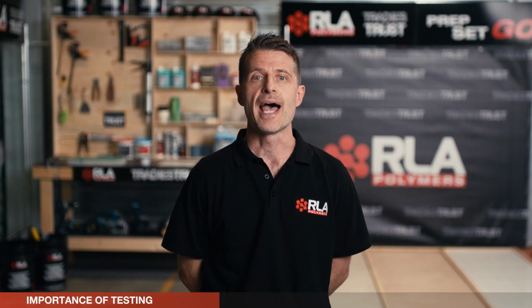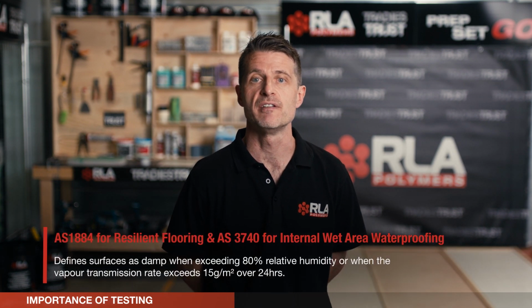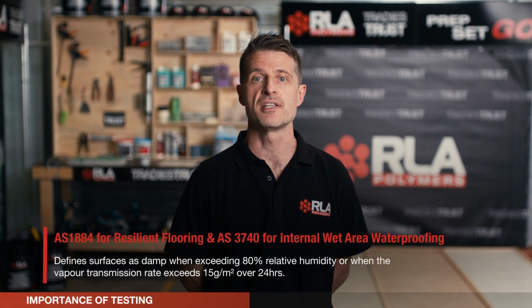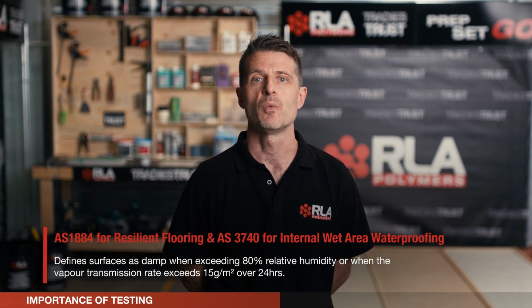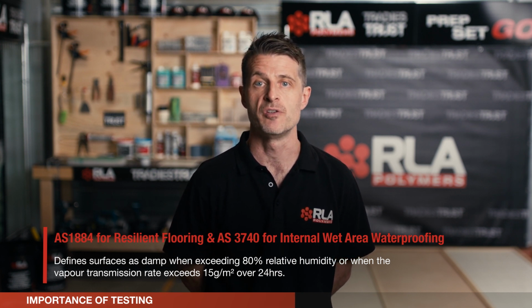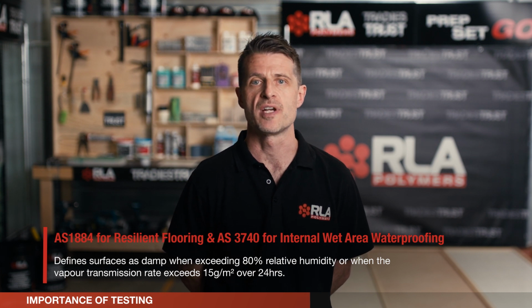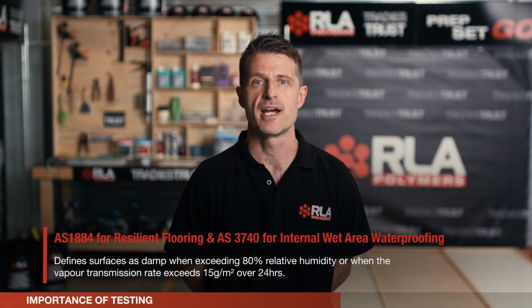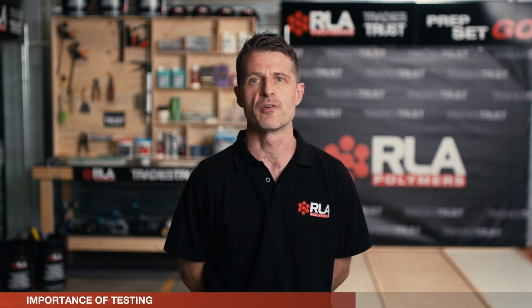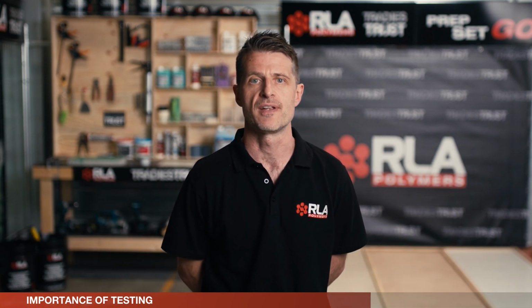So, AS 1884 for resilient flooring, for example, and AS 3740 for internal wet areas define surfaces as damp when exceeding 80% relative humidity or when the vapor transmission rate exceeds 15 grams per metre squared over 24 hours. Now this translates to around 4.5 to 5% moisture content.